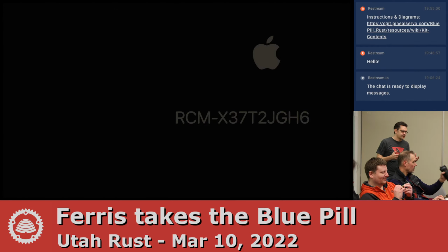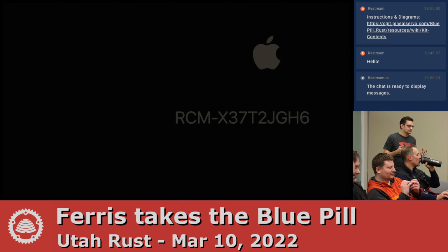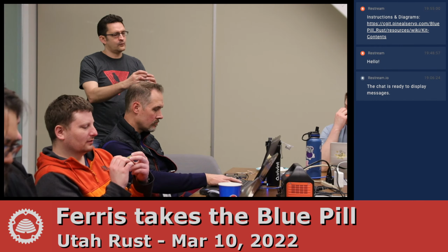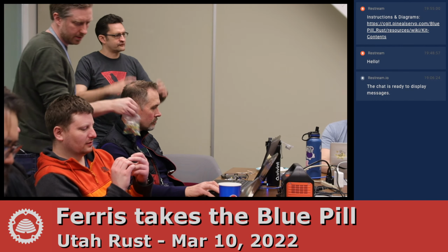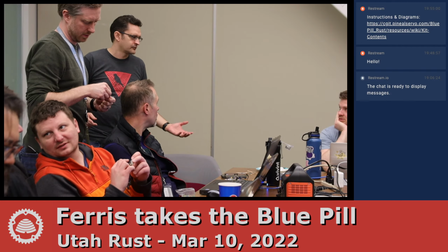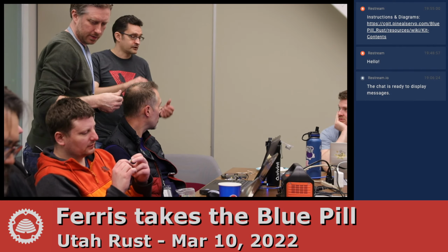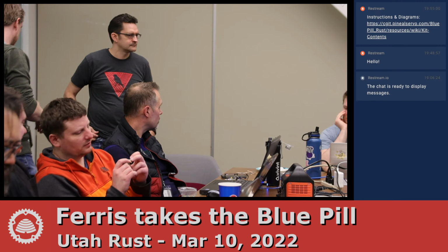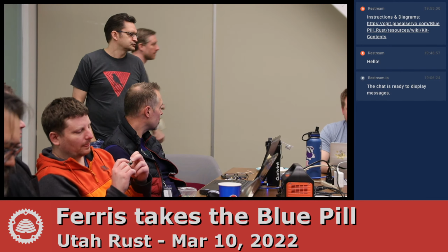The embedded graphics simulator lets you run it on your PC using SDL. So you get exactly what would be on your tiny little screen on a much bigger screen. And you can use your mouse wheel to simulate the rotary encoder. And the rotary encoder has a push button in it. So pushing any of your mouse buttons works like pushing the rotary encoder.